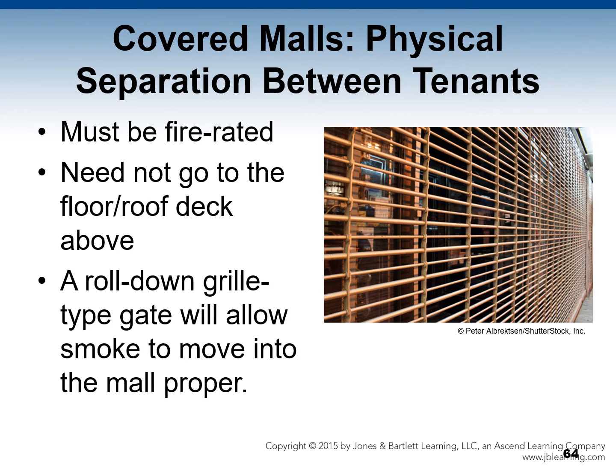In terms of physical separation between tenants, that separation must be fire-rated, but it need not go to the floor or roof deck above. A roll-down grill type gate will allow smoke to move into the mall proper from an individual store or stores.